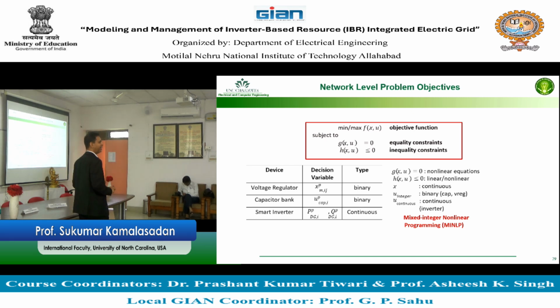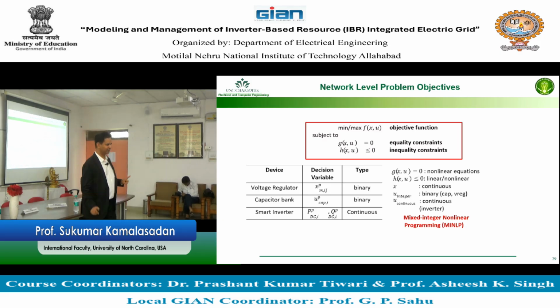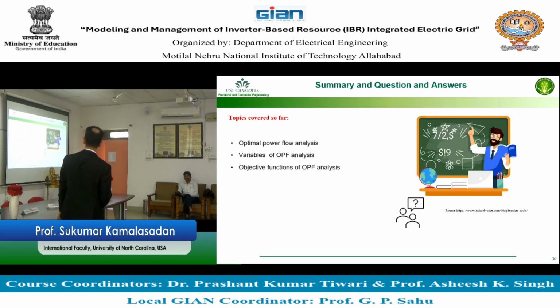So ideally, an optimal power flow problem is non-linear in nature. If you have a decision variable which is binary, like a capacitor or something, then you must use mixed integer non-linear programming. Unfortunately, this is one of the hardest problems to solve in the optimization world.